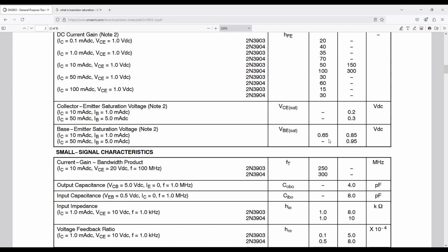I don't know if I'm going to test this out right now, but what I'm thinking is that we know the LED in the OR gate does not turn on, but the NOT AND gate is working fine. So maybe we should output both of those values to our final AND gate and just see if it works, the exclusive OR. So maybe I'll make a new AND gate, or I can put it into our old AND gate using some cables and see what happens.